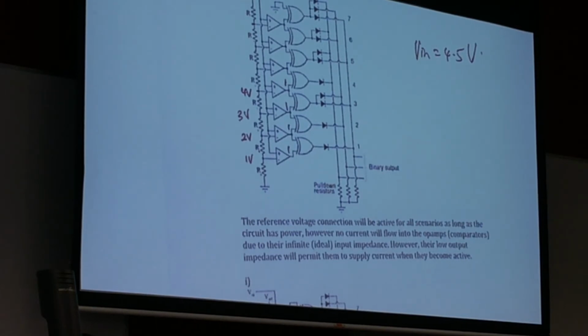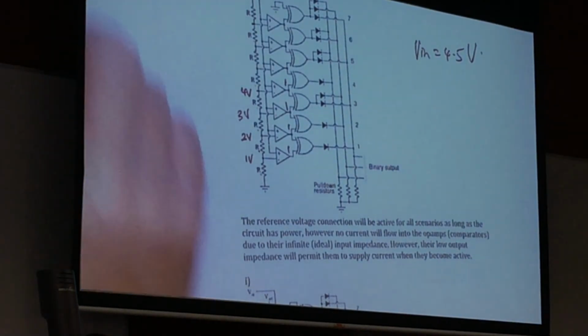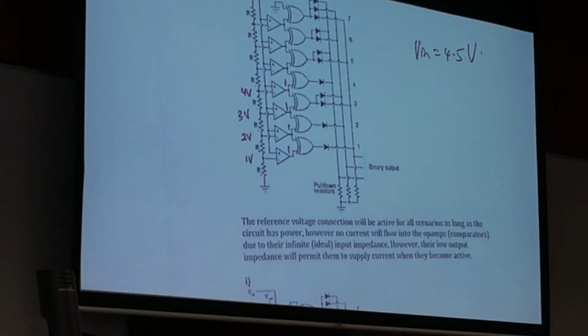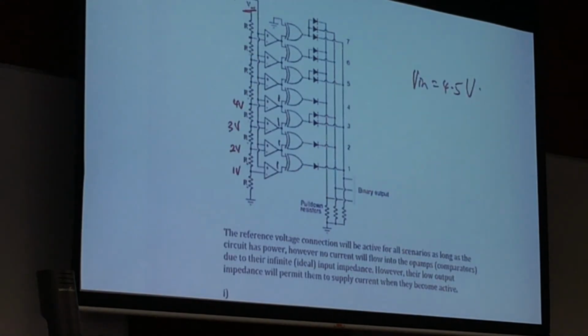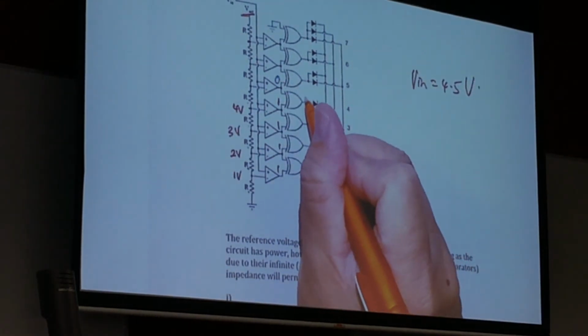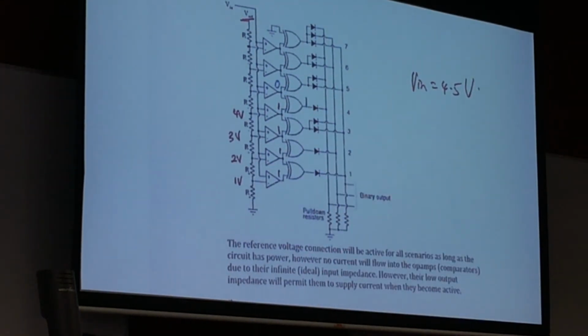Now the next thing you need to note is that this gate is exclusive OR, meaning it must be that either one of the inputs is a 1. Both 1 or both 0 will give 0. Is that clear? So where are you going to get a 1? Well, in this case, this is the last one that is 1 and the next is 0, so this will give you a 1. Is that clear?